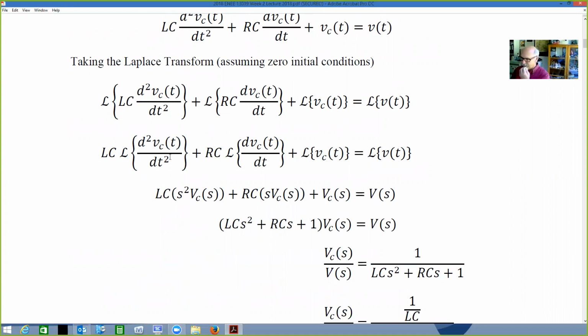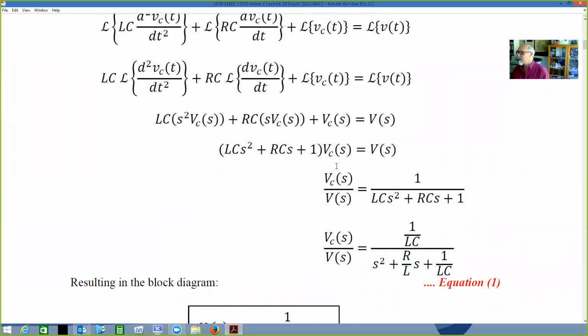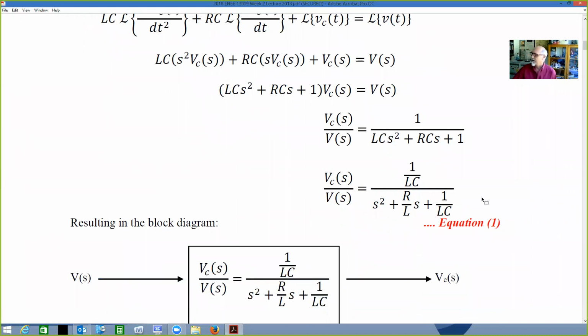the bit that you need to concentrate on. So why I do this is to make sure that you're concentrating just on the bit that you need to concentrate on. So do that. You've got to look up your tables, and you'll see very quickly that they are your Laplace transforms for each of those values. Then you're rearranging, and the relationship you want, as we said, is the change in voltage across the capacitor over the source voltage. So now we have this equation 1.